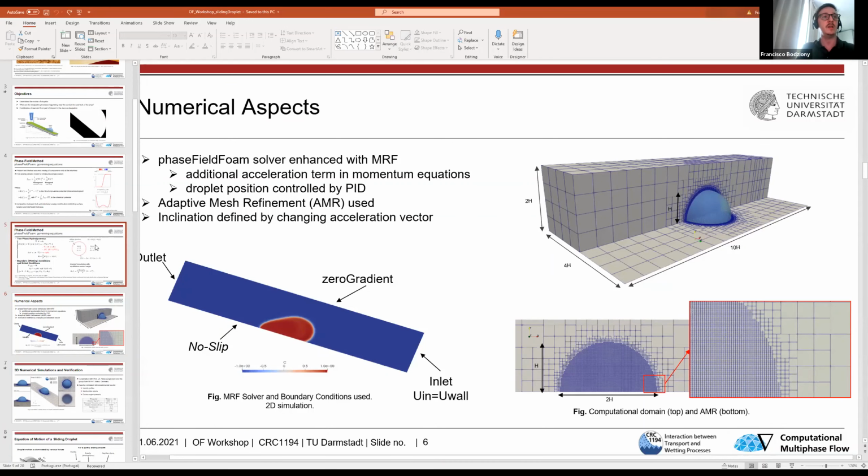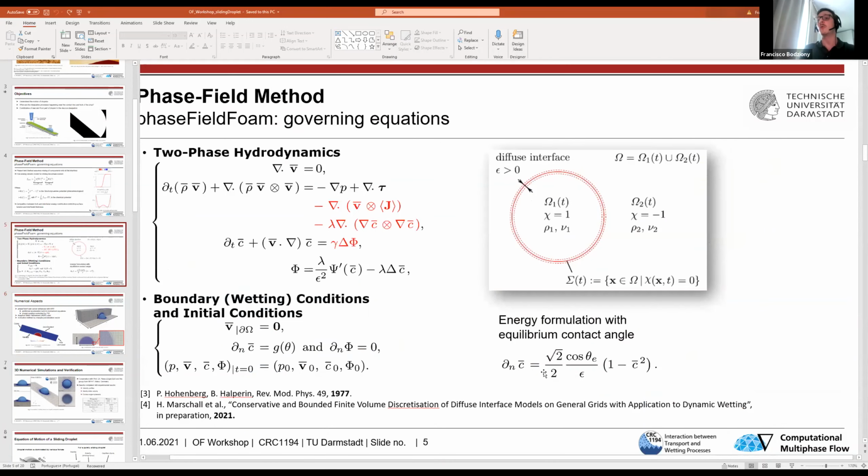As I've explained, the boundary condition arising from the order parameter only has as input the equilibrium contact angle, and by having this and the contact line speed, it's possible to model the dynamic contact angle and also the hysteresis. Okay, so it is a dynamic contact angle formulation in itself. Yes.